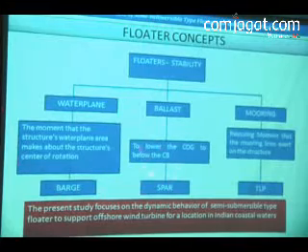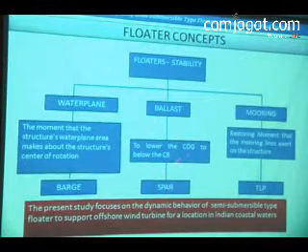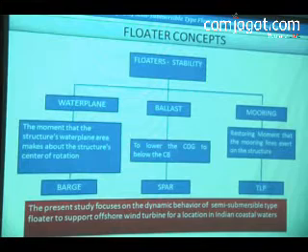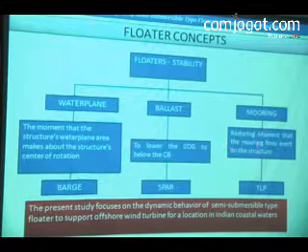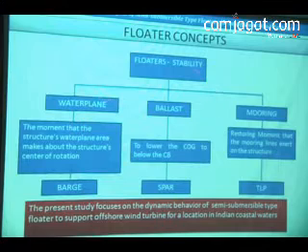And actually, there is a floating offshore wind turbine spar which exists, I think, if I'm not mistaken, in Denmark or Norway. And there is a concept based on the TLP, with the restoring moment from the mooring lines fixed on the structure. So we can achieve floater stability with all these concepts.